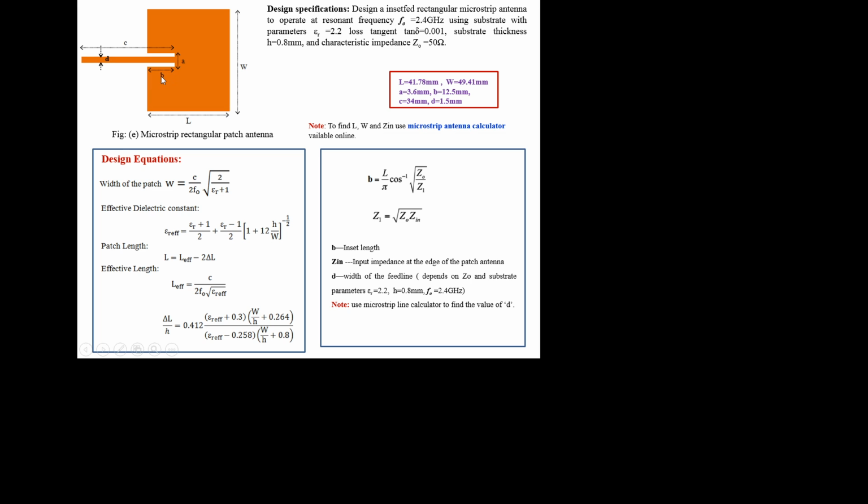Okay, so we have to optimize the value of b, just increasing or decreasing the value of b above and below this value, to get optimized radiation from this antenna. While doing simulations, for this problem whatever is given, we got 9.25, but if you set b to 9.25, maximum radiation we did not find. So what we did is we optimized b by increasing its value.